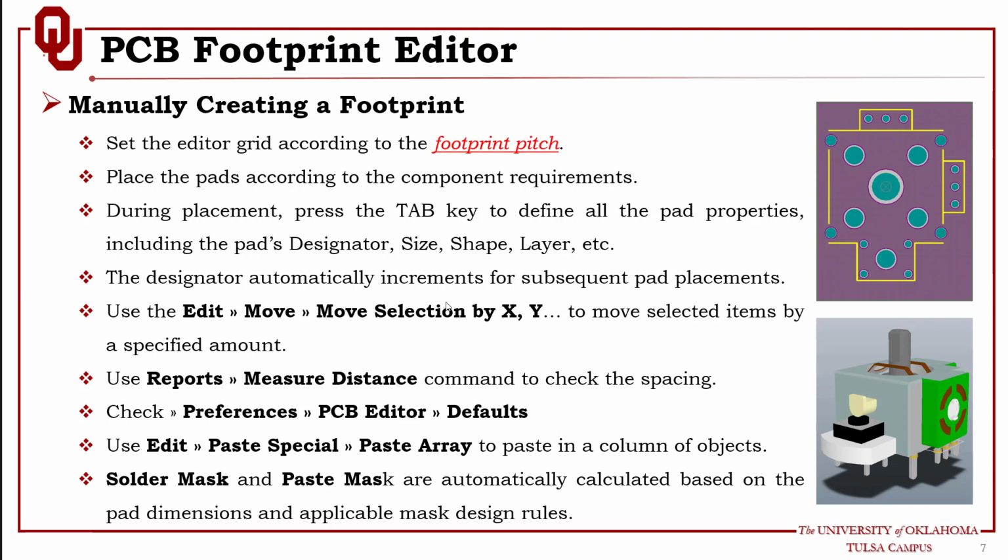Now the increment can also be defined in the preferences. By default it's incremented by 1, but you can still change that, as we did in the schematic. You can change that in the preferences here under PCB Editor defaults.